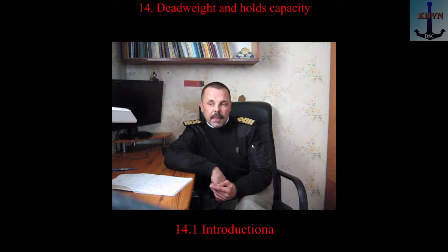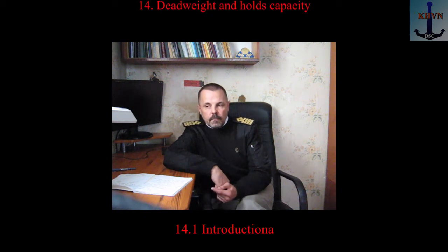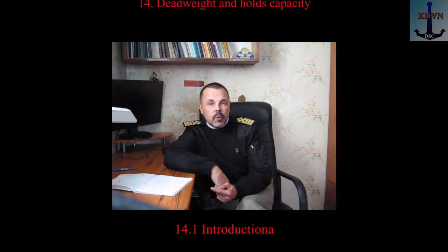If you do not know how to calculate your landing and stability manually, this is not so bad. In the end, everything is calculated by the cargo computer. The trouble is if you do not know how to evaluate what it counted. I hope that the first part of the course will help you with this, and you will be able, looking at the final table and the static stability diagram, to draw a conclusion on the stability, the readiness of your vessel for a voyage.